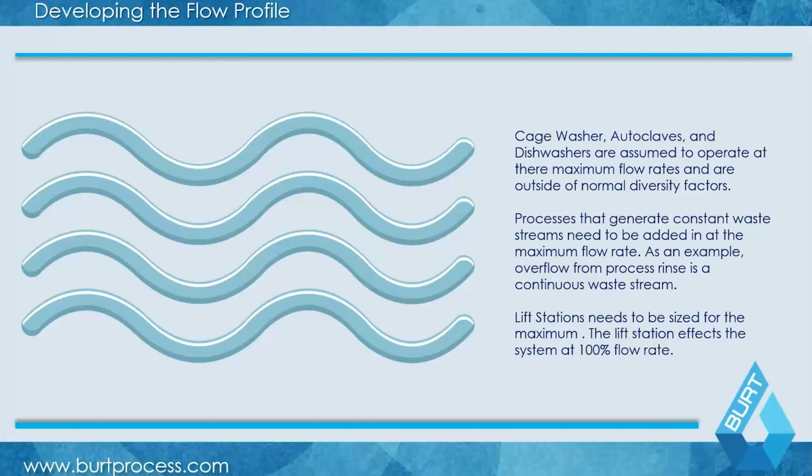And we do this in a lot of different ways. One way is looking at what you have for lab sinks. You have your lab sink or fume hood, which can have a cup sink tied into that. That could be dishwashers, autoclaves, semiconductor tools, clean room environments, vivariums. And you're saying these are not all going to dump at the same time. If you ever walk around a lab or industrial space, half the things are sitting idle. We look at all these different examples and we assign a flow rate to them, and then we assign a diversity factor to them.